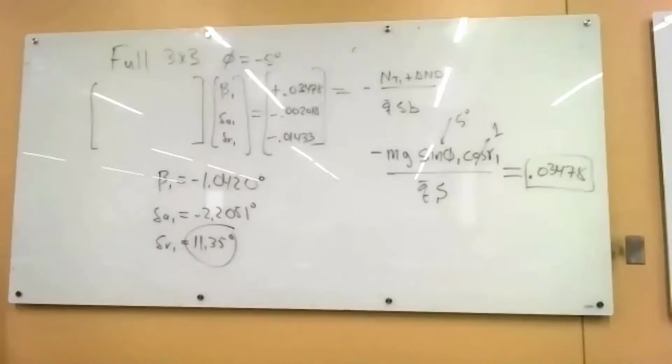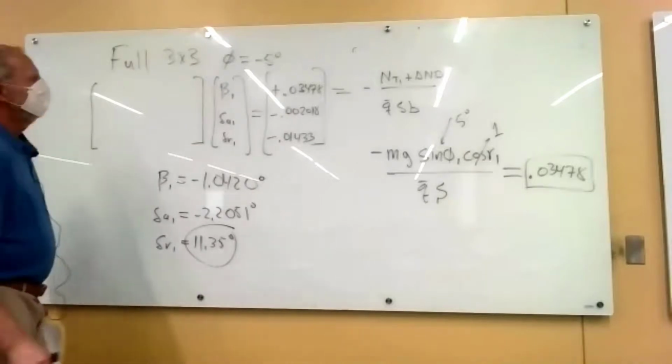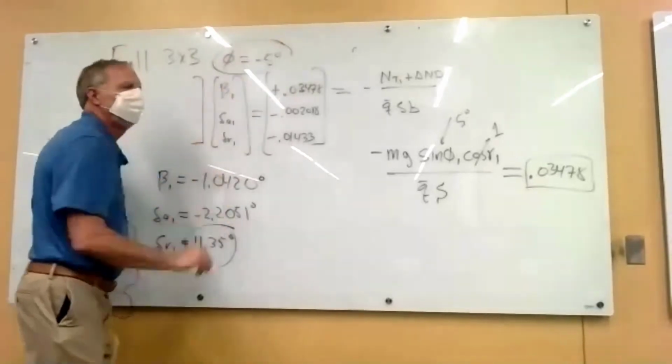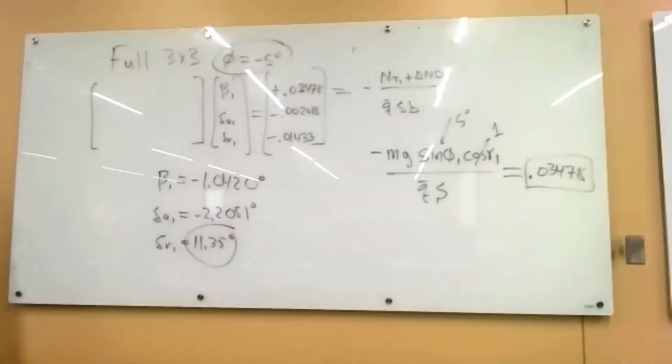So again, the logic here is that they calculated this for 0 bank angle, realized they could allow the pilot to bank 5 degrees. If they do that, then that approximation actually matches the 3 by 3 solution pretty well. And again, this is preliminary design. They will do wind tunnel tests and flight tests to validate the approximation and the numbers.